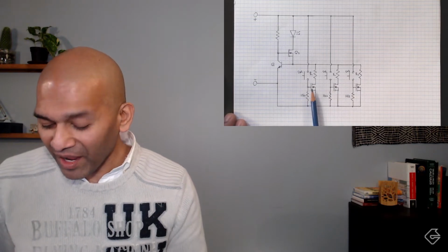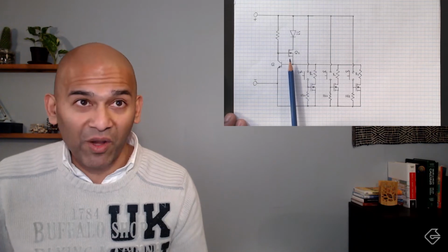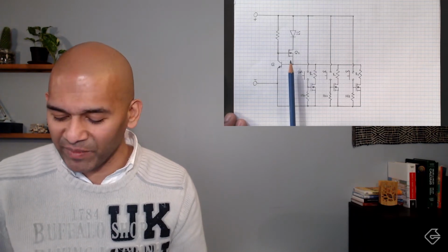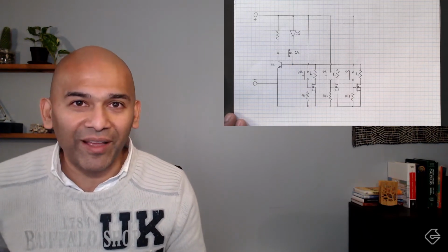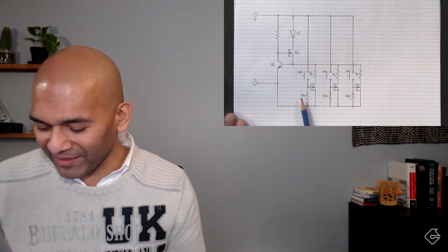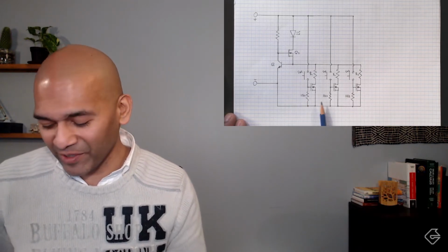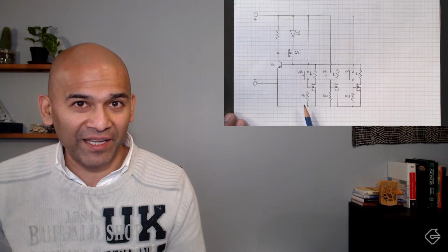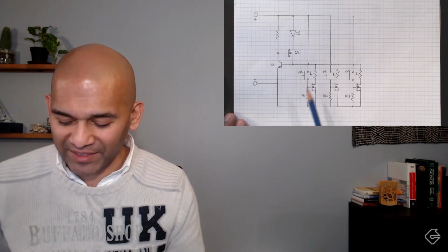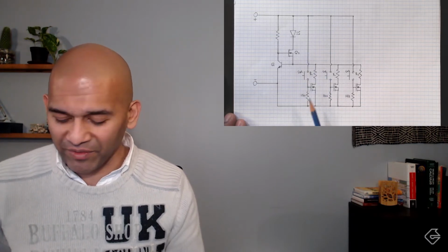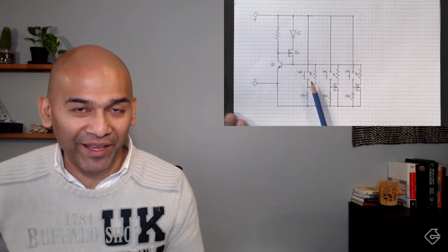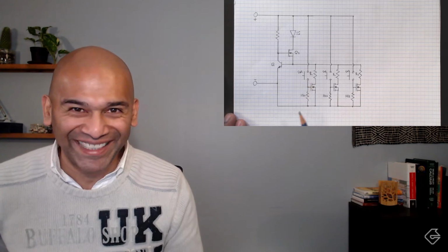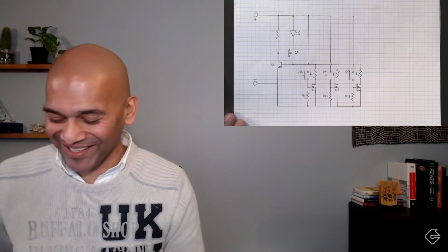So I'm going to use the exact same MOSFET that I have already in my circuit. This, if you recall from prior, was a BS270 MOSFET. I'm just going to use the same one. Why? Because I got them. And the other reason, I also put a 10 kilo ohm resistor here. I'm using 10 kilo ohms for 2 reasons. One, because it keeps the current very low through the switch, which is what we want, half a milliamp. But also, I got them. I got 10 kilo ohm resistors here, so that's what we're going to use.